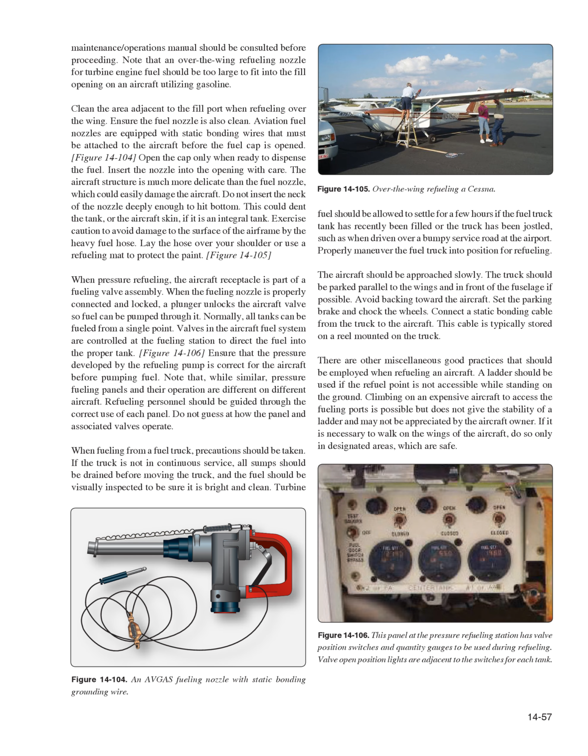When fueling from a fuel truck, precautions should be taken. If the truck is not in continuous service, all sumps should be drained before moving the truck, and the fuel should be visually inspected to be sure it is bright and clean. Turbine fuel should be allowed to settle for a few hours if the fuel truck tank has recently been filled or the truck has been jostled, such as when driven over a bumpy service road at the airport.